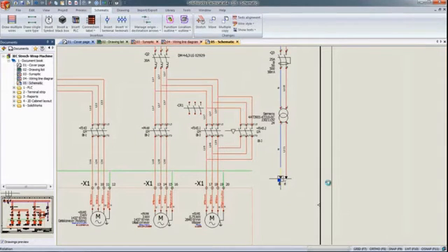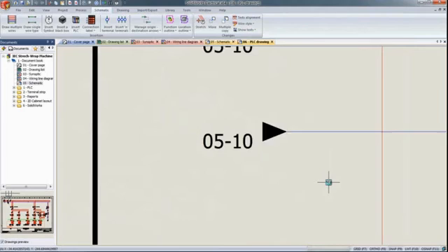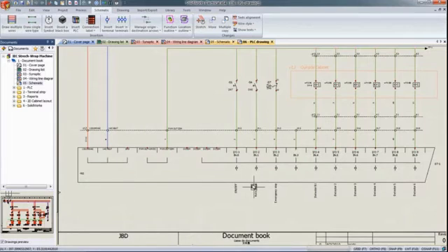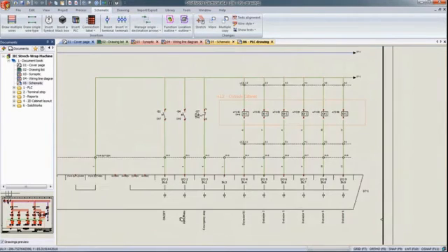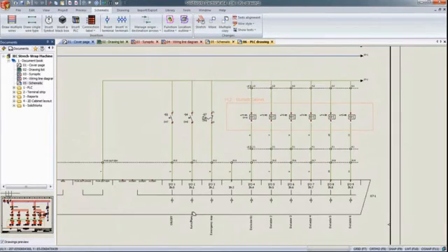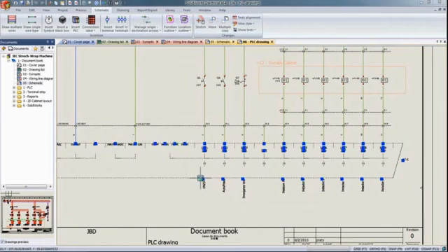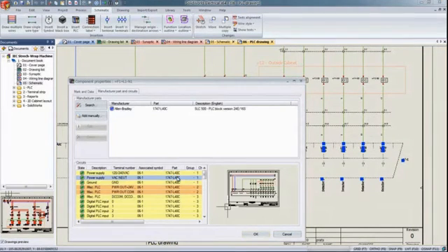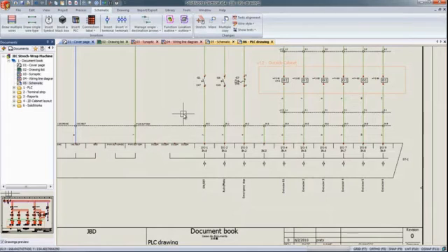Now, this schematic does include an off-page reference from the output of this power supply. By clicking on the arrow, I can simply navigate to page 5, where we'll find the first page of our PLC documentation. SolidWorks Electrical includes comprehensive tools for managing and documenting large I/O devices like PLCs or high-density connectors. And on this drawing, we'll see more use of the location outlines for these external sensors, and we can also drill into the PLC component itself and see all the I/O for the entire device, not just what's on the screen right now.